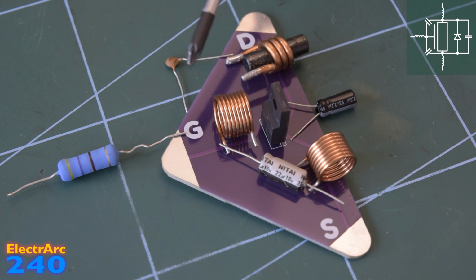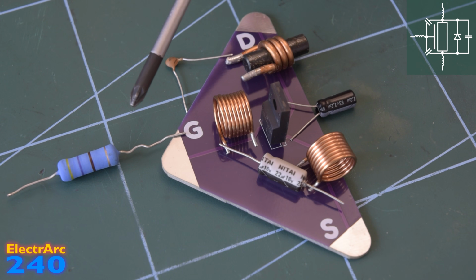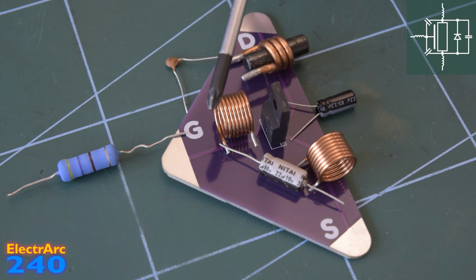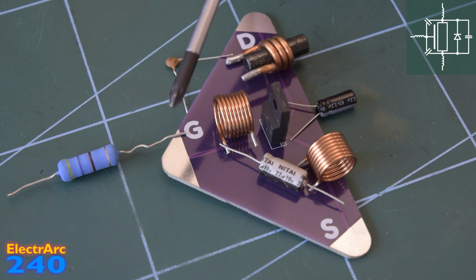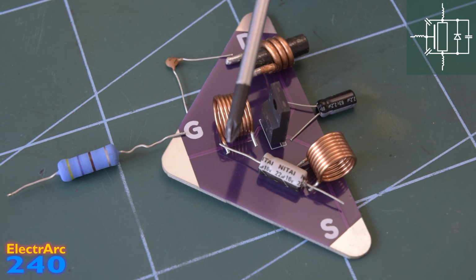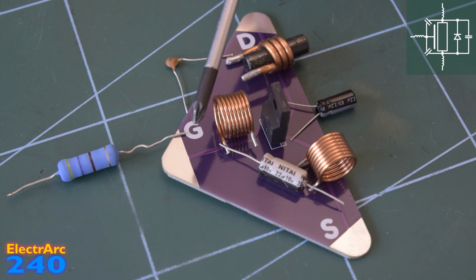There's also something called an active Miller clamp that's another fancy gate driver feature, a bit like DSAT. And that's essentially like a second gate driver with no gate resistance. So it's really strong for pulling the gate down and keeping it down. This second gate driver only kicks in once the gate has been pulled below a certain voltage. So that means it doesn't result in the ringing that you'd expect using no gate resistor.